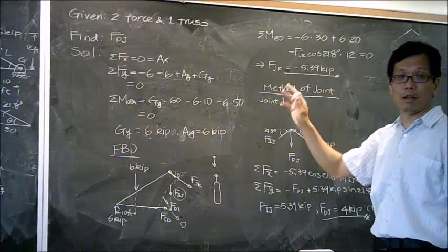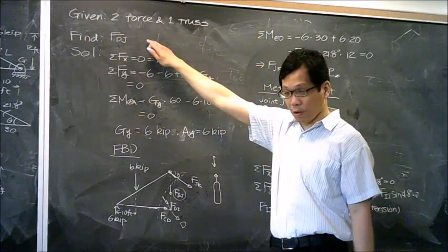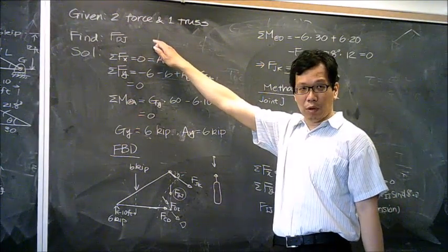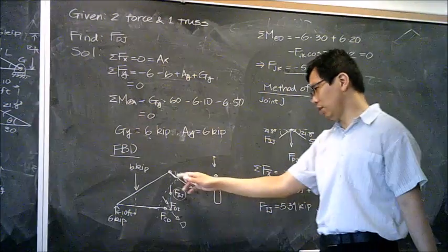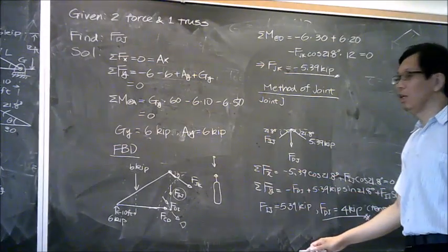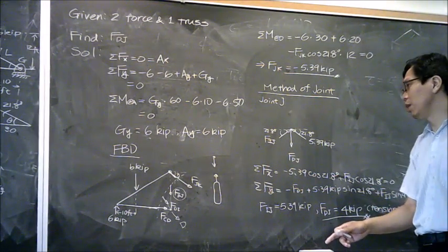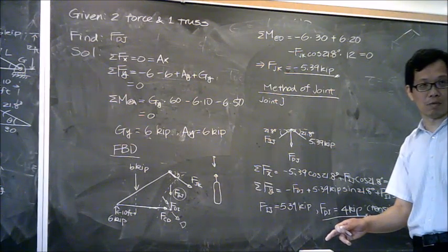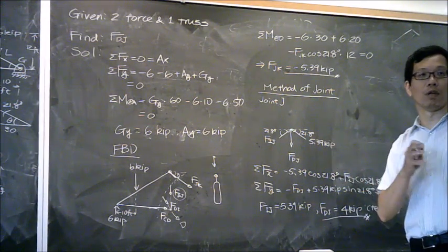You should be able to get all the information for the member you are interested in. If it's not the case, then consider using method of joints. Combine both methods together to eliminate the unknowns in your system, then you should be able to find everything straightforwardly.